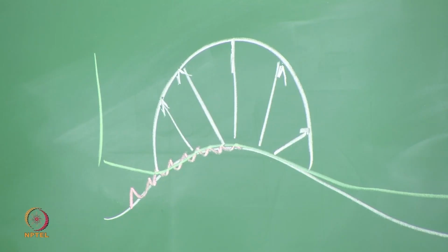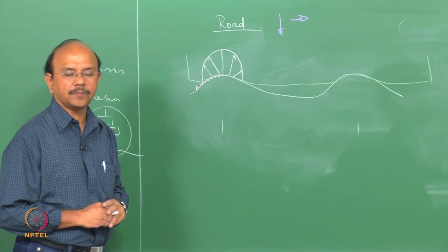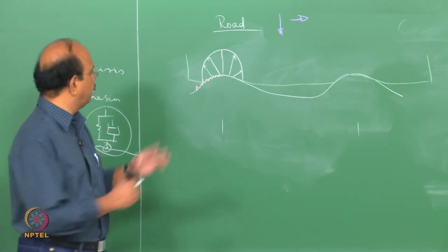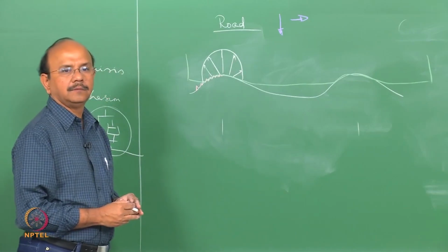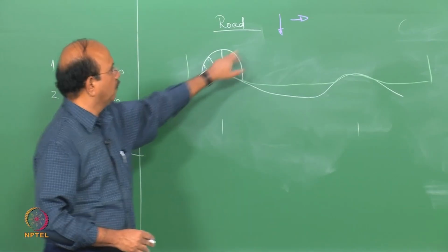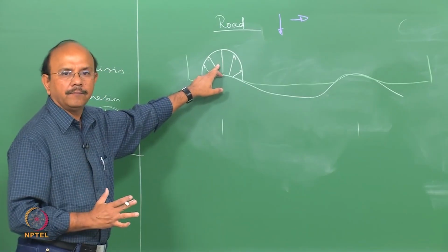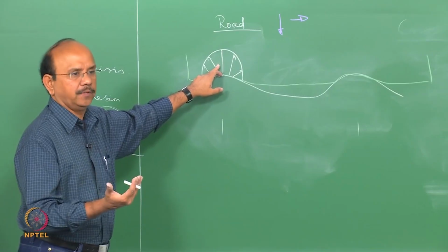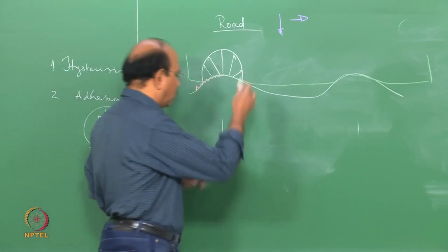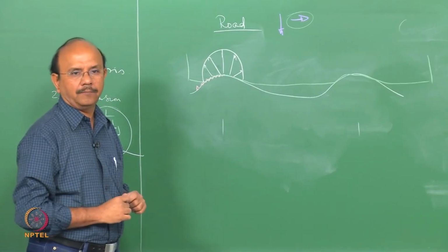Now, when there is a lateral force that this block is subjected to, then obviously this kind of symmetric distribution, which equilibrates the normal force, is no more maintained, and this pressure distribution becomes unsymmetric, because it has to now equilibrate that lateral force as well.